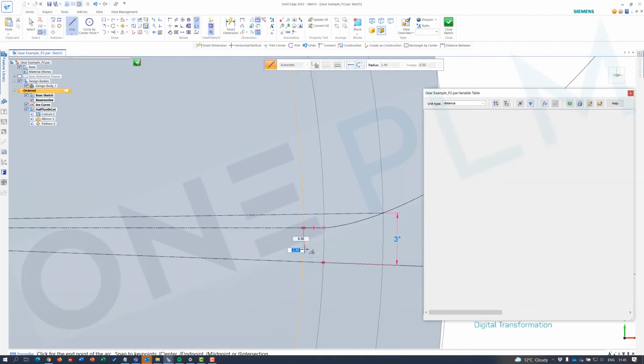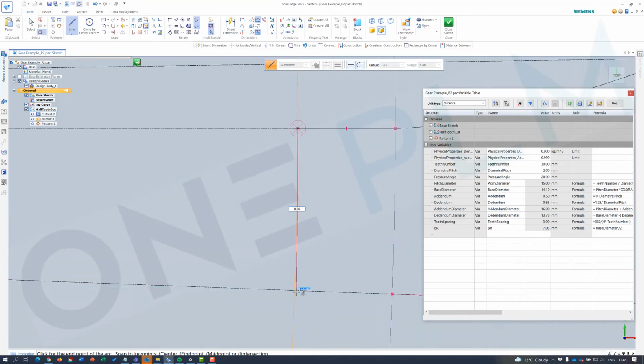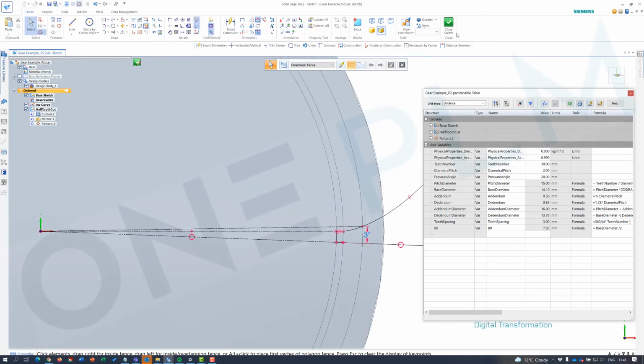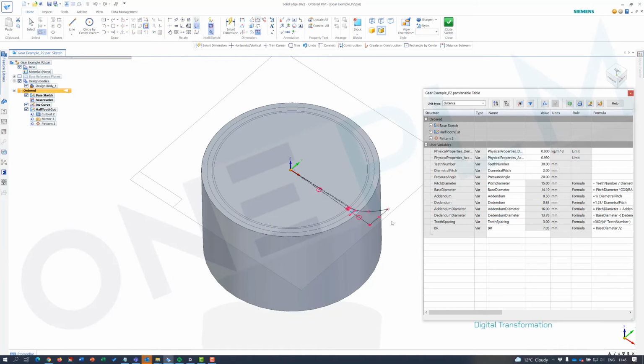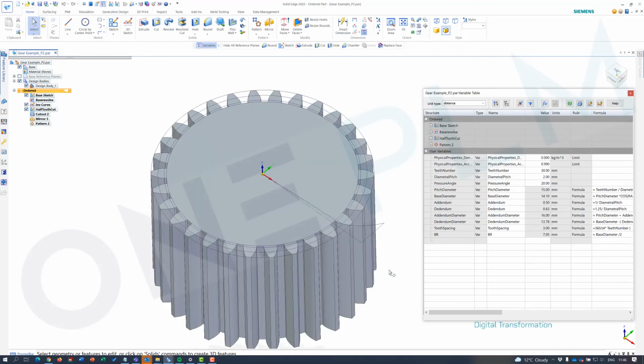And then there I'm also going to go and use an arc command. And again, I'm going to go and pick the intersection point on there. And that should go and find the appropriate intersection point that we need. And then I'm going to go and take that line back to there. Notice we get highlights of orange showing that that is linked to those. So if we close that, we might have to redefine our cutout. Hopefully Solid Edge isn't going to ask us to go and redefine our cutout. And we've corrected that little issue.